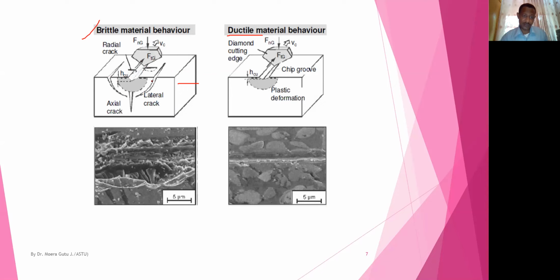So the machining chip will form in this direction, whereas the crack may form as an axial crack inside the workpiece material, which is not good. This is a lateral crack in this direction. This one is more important, it is good, it is the machining direction. So you see, the uncut chip thickness or the depth of cut matters in how we can avoid the axial crack, which should be avoided in machining hard materials. Okay, is it clear? Okay.